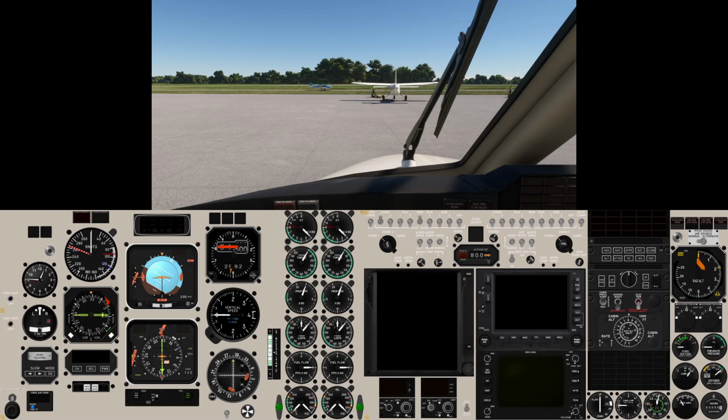So what I've done is, when you touch the area in and around the annunciator, they're not buttons as such, but just to make them a bit more readable, you can touch the actual annunciation and it will make it a fair bit bigger. So you can read what it is, but you'll get to learn what they are anyway in terms of their position and the colour. At least you just have a glance over. If it's black, you're all good. If any are on, then obviously you may need to be aware of what they might be. But generally in flight, they will mostly always be off.